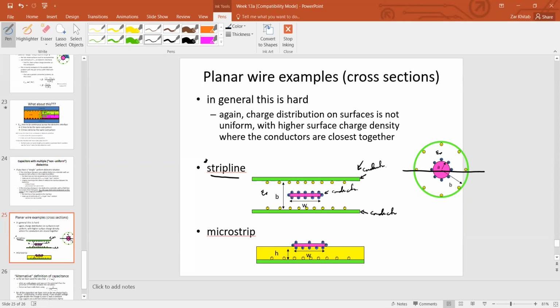Strip line, on the other hand, these days is used for inter-component communication on a transmitter or on a receiver. So it's inside the board. It is fabricated on the board. You may fabricate them on your mobile phone circuit boards to have communication between two different components on a mobile circuit board. So they are very small. They're used for very small distances. But the behavior is very refined. Probably the best of all the metallic transmission lines.